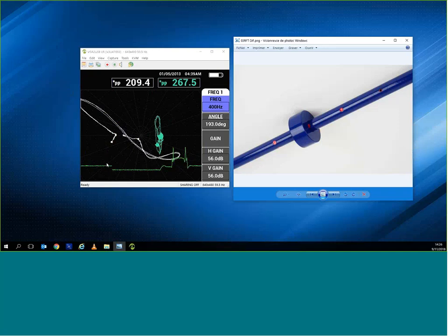As I mentioned before, if the defect is completely hidden by the support, it's going to be very difficult because there's a lot of attenuation going on with the magnetic field into the support. But if it's close, you can still see it, and these are the air defects, which I'm just scanning to show you what's going on. And that's air liftoff. So that is remote field differential.